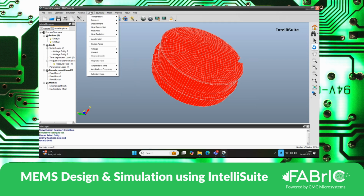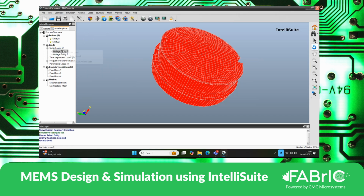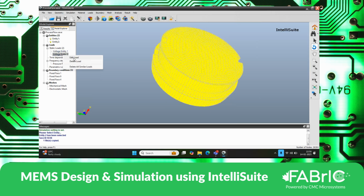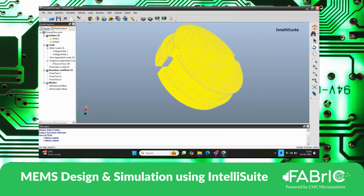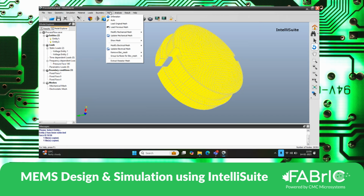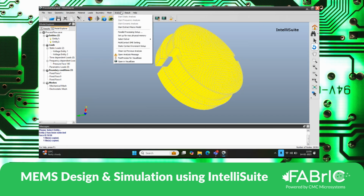Then I go to loads, voltage. The voltage has already been defined. Voltage entity for one, let me check its value. One is 0, another is 500. Probably this is for the simulation, I guess. Once that is done, we fix the boundary conditions, and then we mesh the design, and we perform the analysis, start to extract macro model.